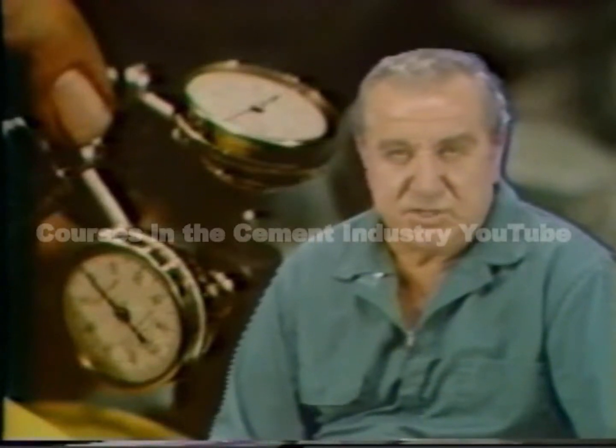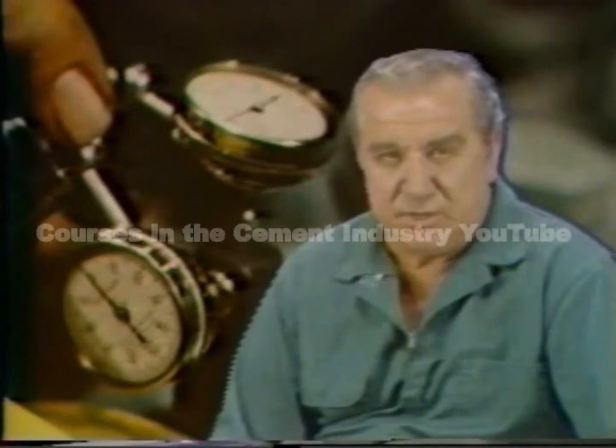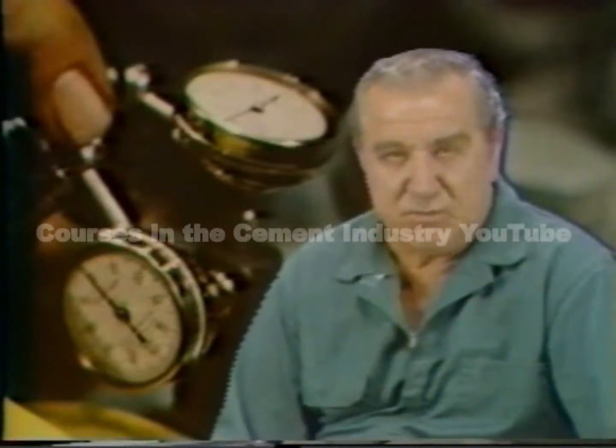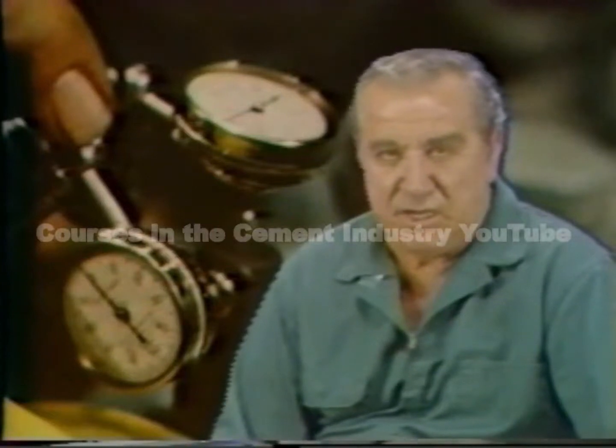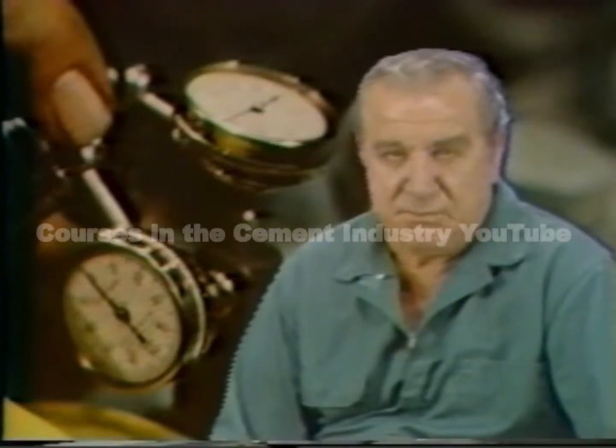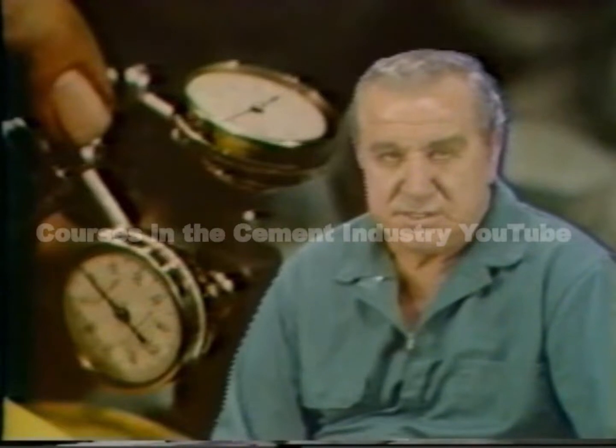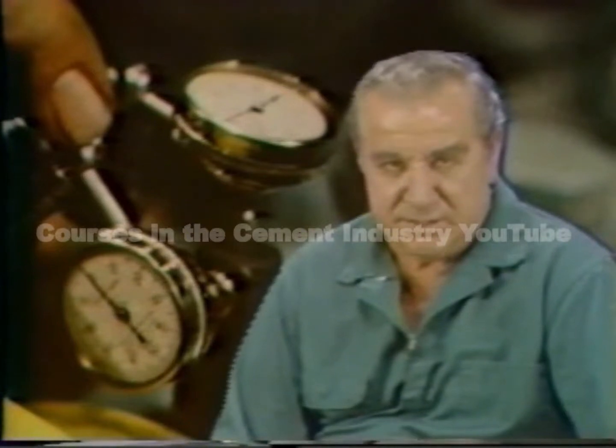This check is looking for an uneven footing on the motor, much like a wobbly chair with a short leg. Others include a piping strain check and cold to hot alignment considerations. A complete explanation of these checks is included in your text, so we won't dwell on them here. Let's get back to the job.